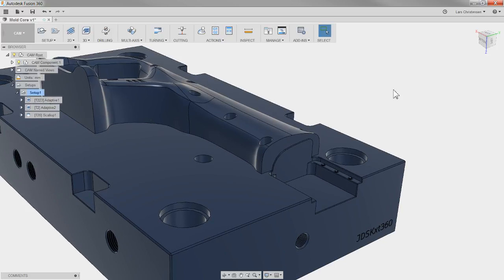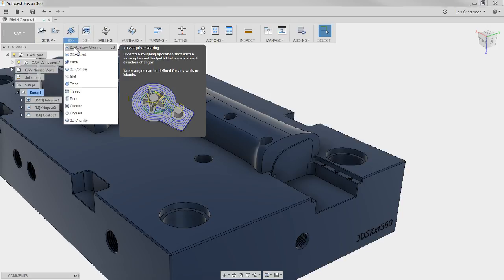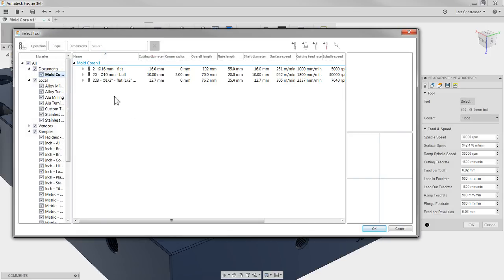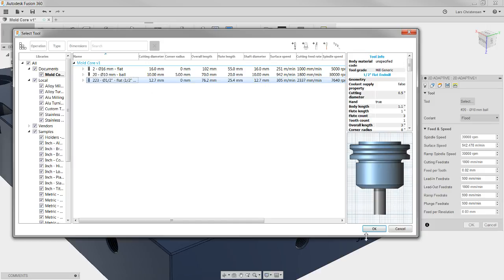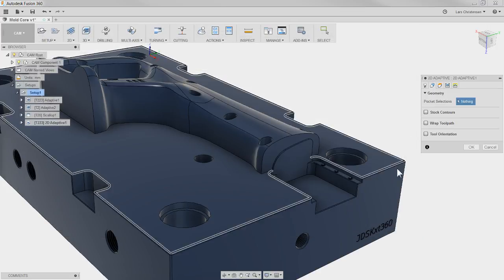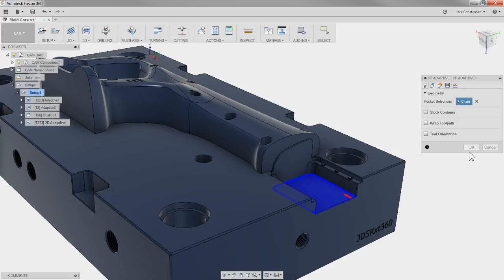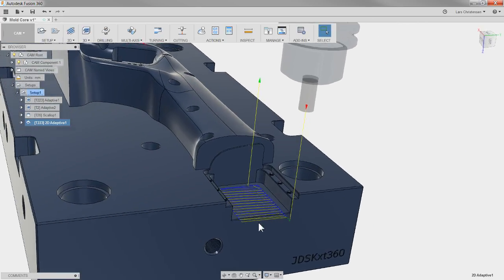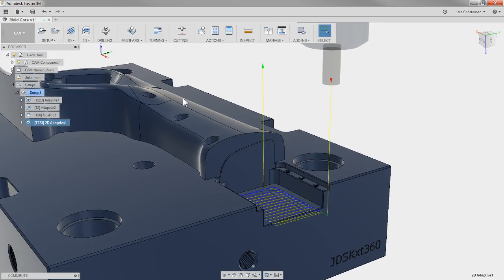Another thing you should be aware of: everything I did so far was the 3D toolpath in here, and that's where you have the pull away or the shaft and holder collision. We do not have that for the 2D adaptive clearing, but it will still show you. So if I select that same half-inch end mill, and I say I'm going to rough out this area, I get, actually, I love this toolpath here, it is just phenomenal.